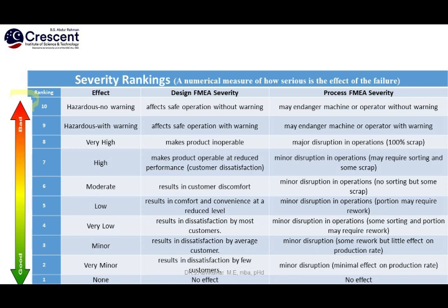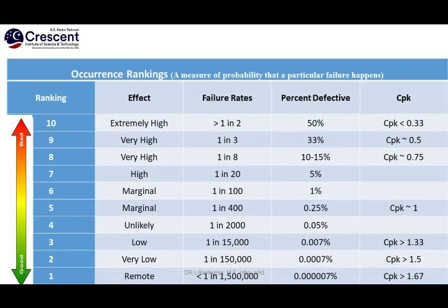Another thing, when it comes to process, we have to connect it with the capability index value. If the capability index value is less than 1.67, then that process is under severe risk. Unnecessary failures are happening regularly; that is what this indicates.